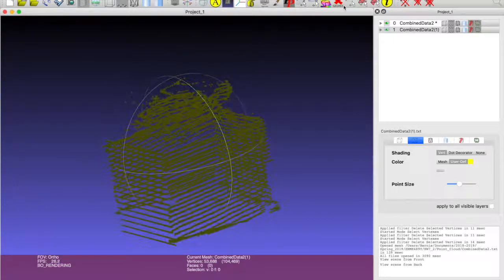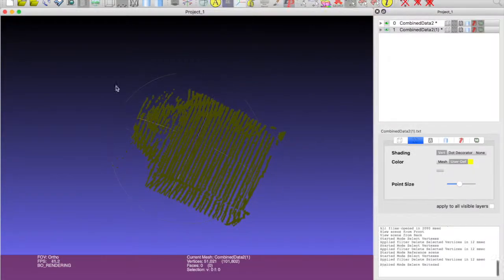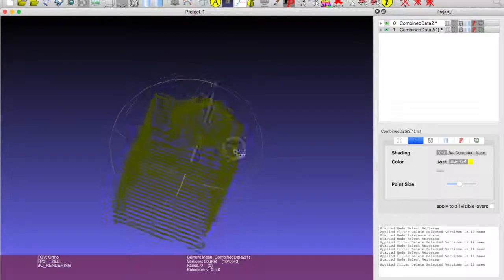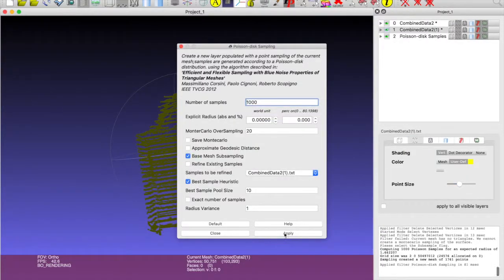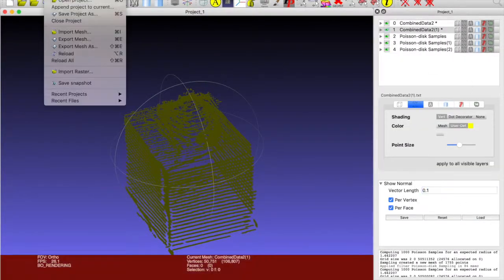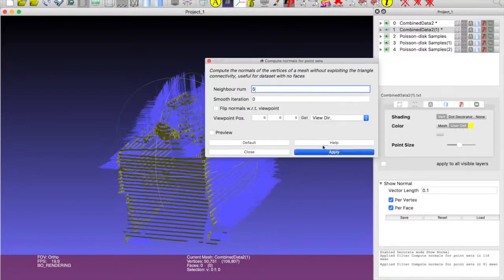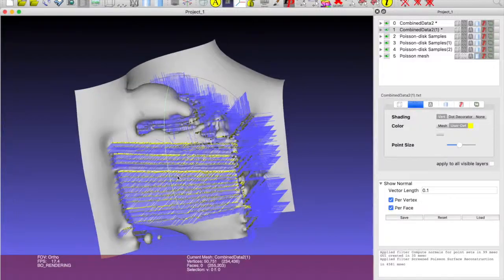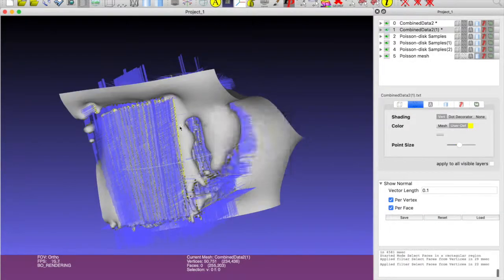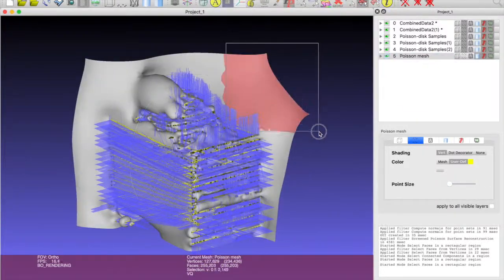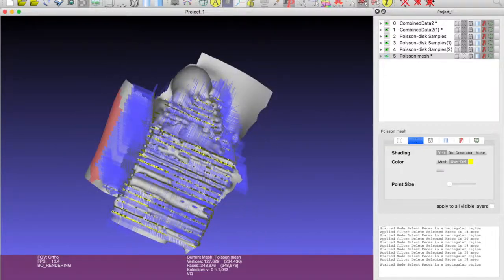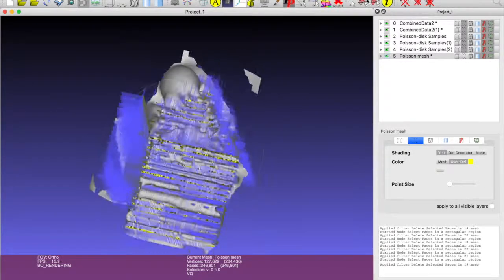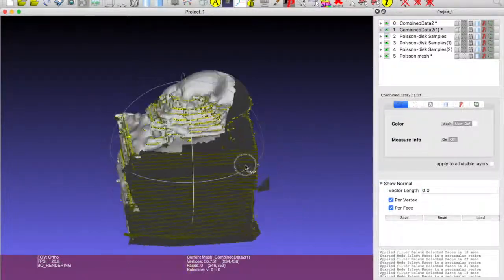I exported the combined 3D point cloud from MATLAB to a text file, which I then imported into MeshLab. I deleted any residual noise left after filtering in MATLAB by manually selecting points. I ran the point cloud through 3 iterations of Poisson disk sampling to further reduce outliers. Then I calculated the normals and performed a Poisson surface reconstruction. I cleaned up the mesh by manually selecting unwanted surface regions and deleting them. This was my final mesh. It isn't great, but you can clearly see the base and part of its shell. I'm sure that obtaining more data points would allow MeshLab to find a more realistic mesh.